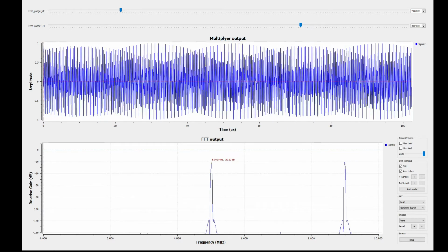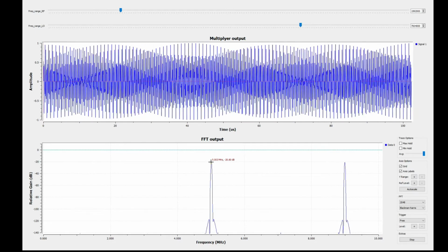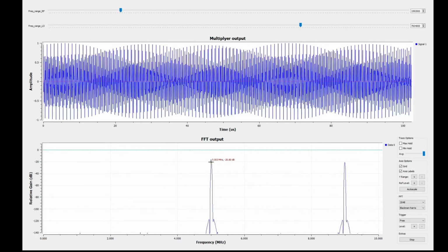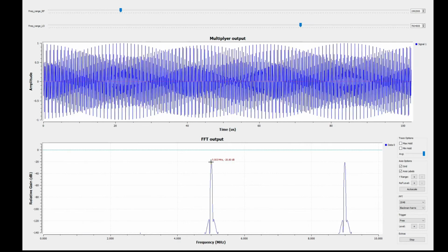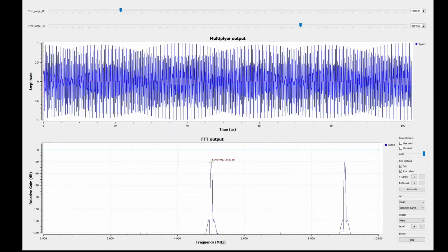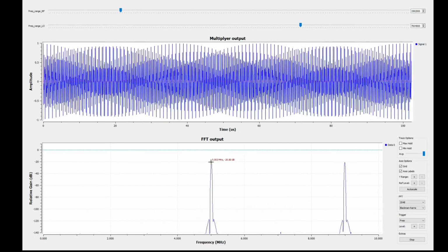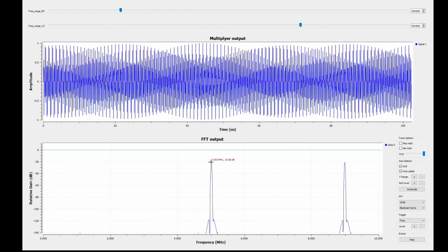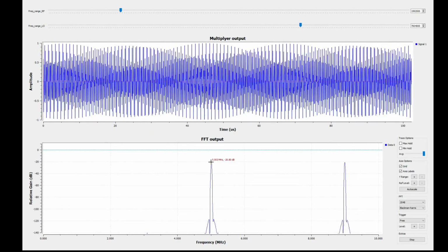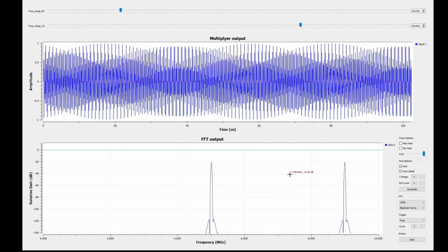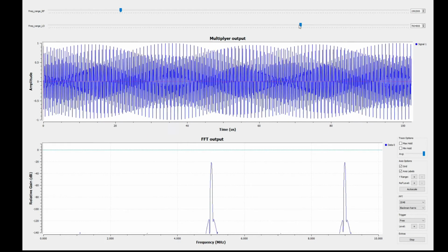If you have a 7 megahertz input in your radio and you have an intermediate frequency of 9 megahertz, you have to up convert it from 7 to 9. If you have on 20 meter a 14 megahertz signal and you need to convert it to 9 megahertz, you do a down conversion from 14 to 9 megahertz. So that's all it is.